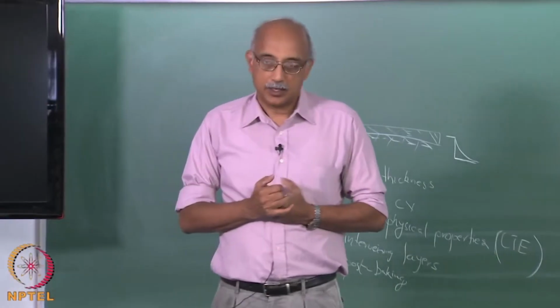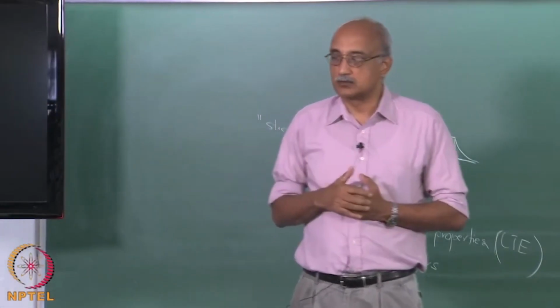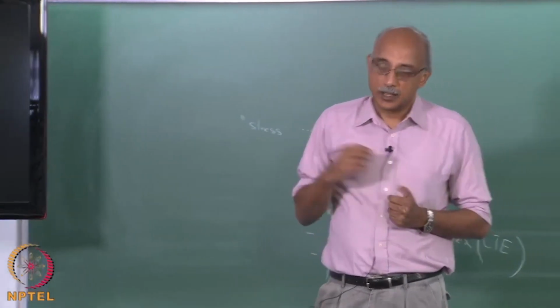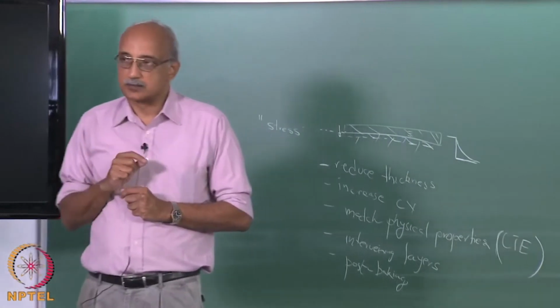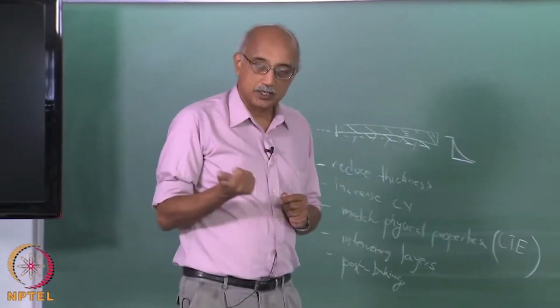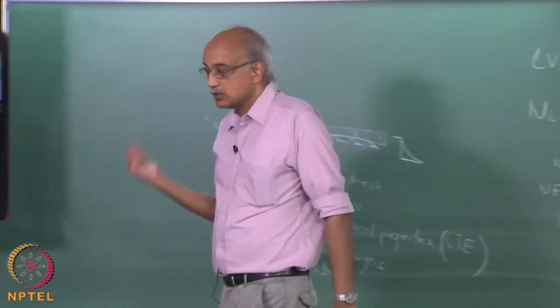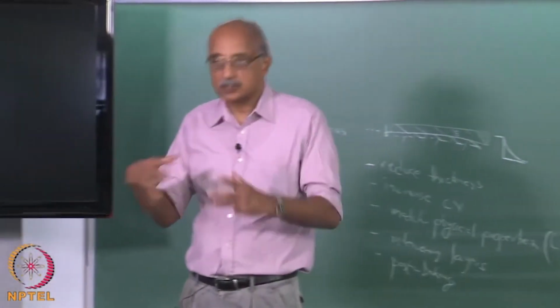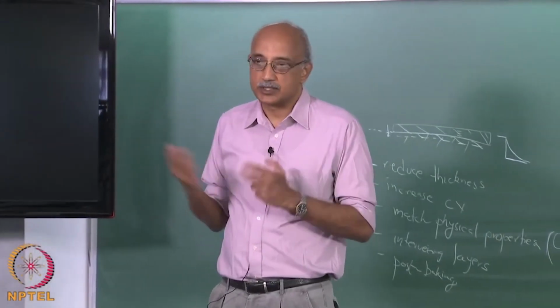Introduce an inert gas as a carrier gas, typically argon was used as the inert gas, and you also introduce appropriate reactive gases, typically HCl, H2 and so on. Then you pack all this into a container and you jack up the temperature to 1000 degrees plus.